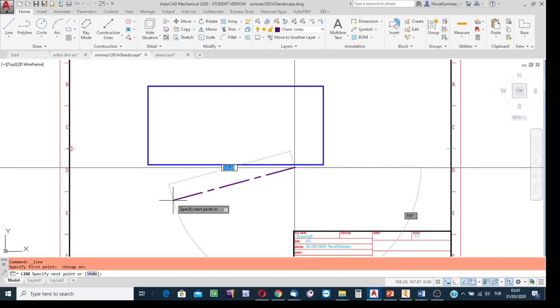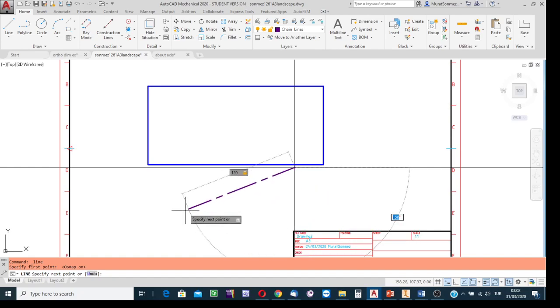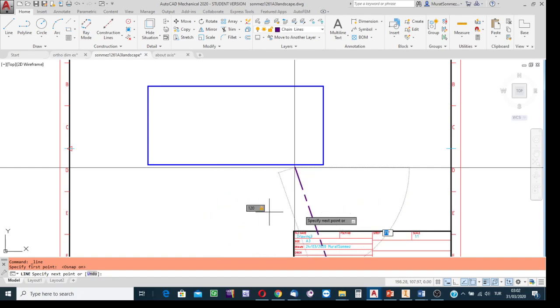I know that the chain line is to be created extended to the left, parallel to the boundary. To make it parallel, and fix its length, in this example its length is 120. Press the Tab key. Write the inclination angle into the angle box.